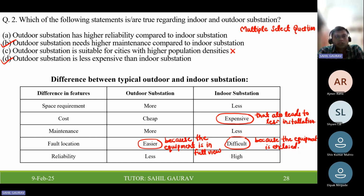C option: outdoor substation is suitable for cities with higher population density. It is incorrect. We prefer indoor substations in higher population densities, and we prefer outdoor substations where we have enough space, like in rural areas or somewhere with low population density.